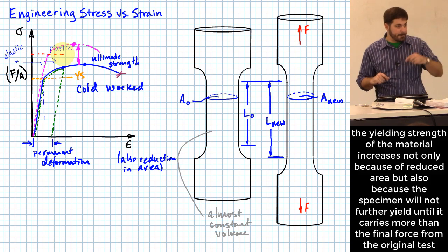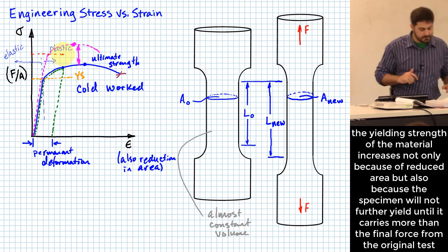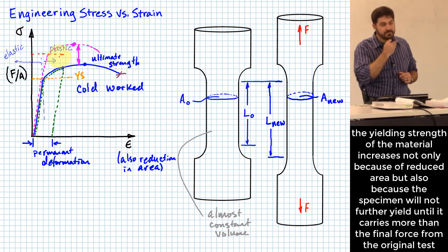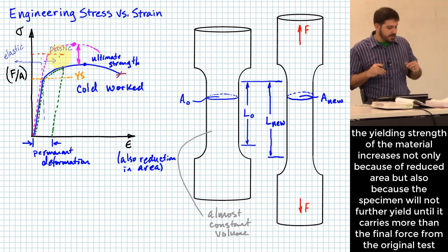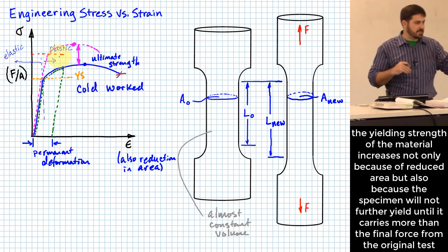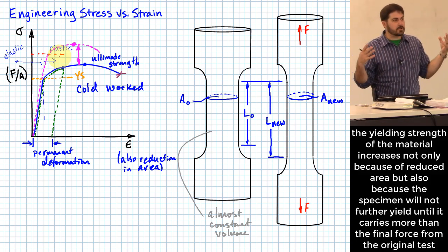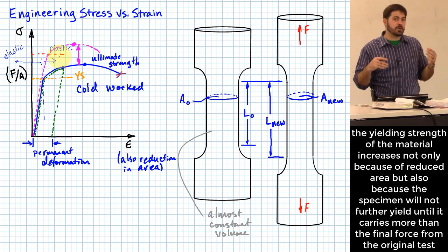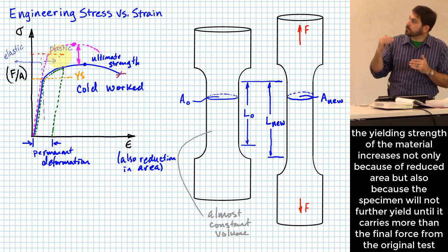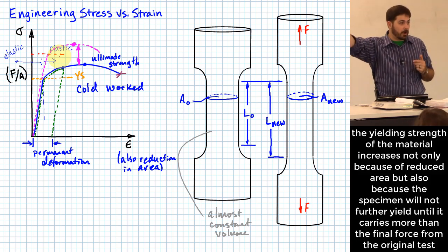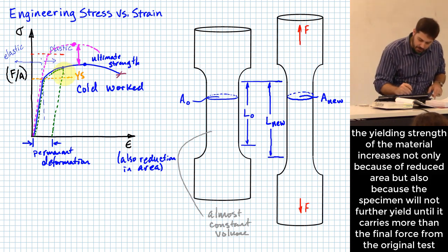So does that mean you're technically increasing its amount of elasticity, but for a specific frame of reference? Okay, let me see if I can rephrase that. His question is, did you just basically increase how much it's in its elastic range? And that is actually a pretty good way to describe it, all right? You've basically increased how much stress can be applied to the material before it begins to plastically deform more, right? And you can kind of see that on the original figure.